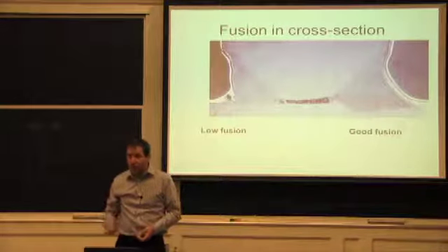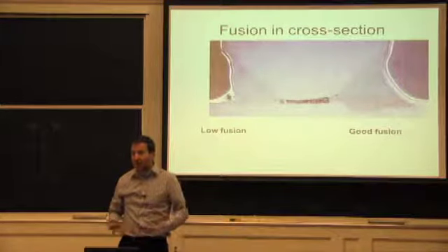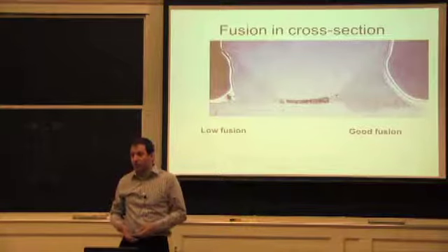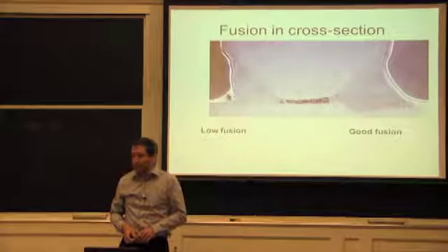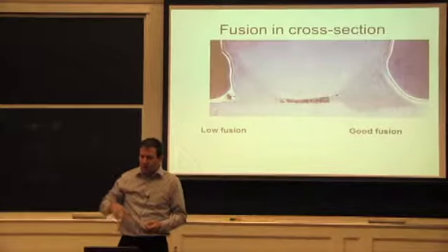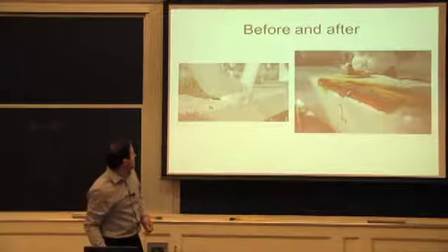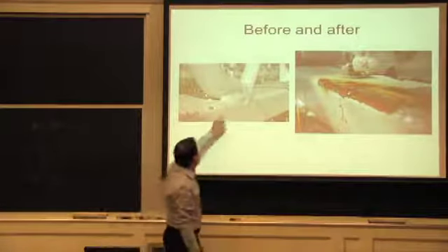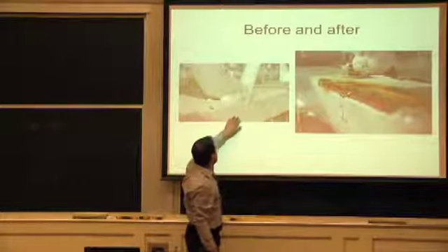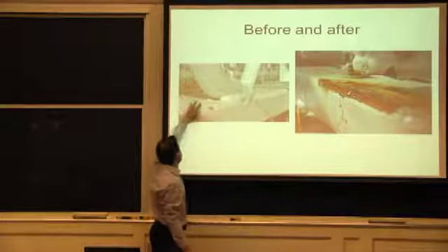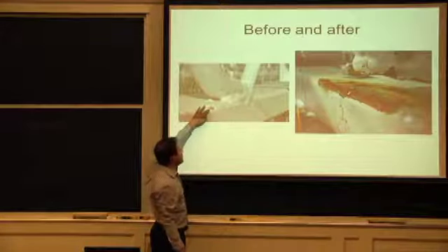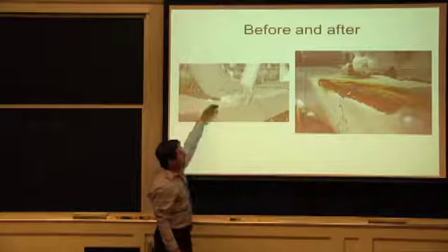But if you weld just from one side, now your chances of a successful connection is going down, and you have a more complex loading because you have eccentricity. So if I take, and that's what they had here. So they had this weld connecting it here, off-centered from that rectangular tube, and they had no welds on the opposite side.